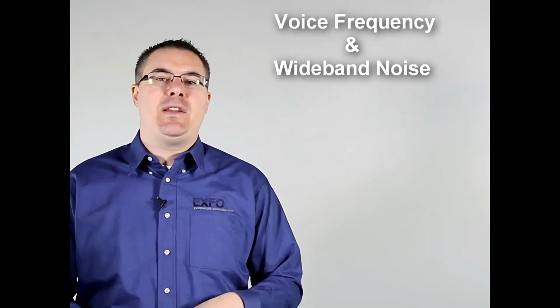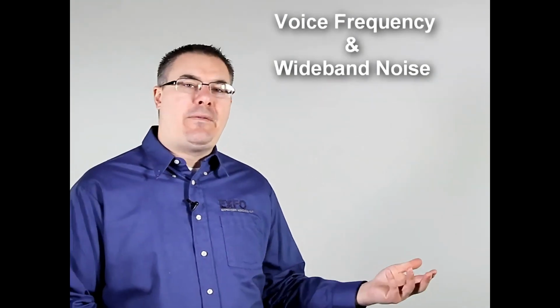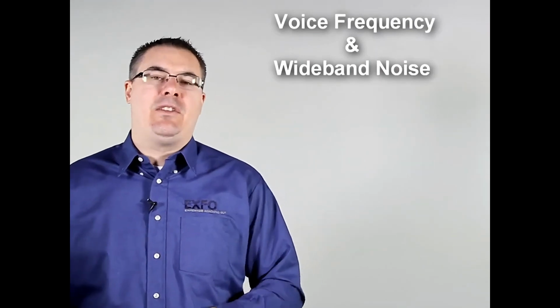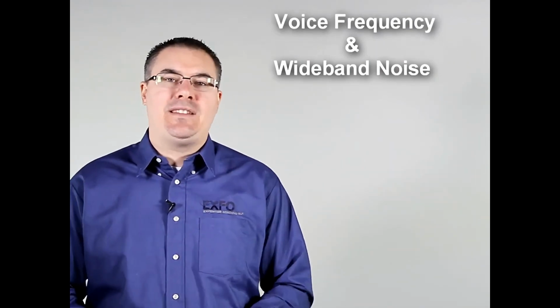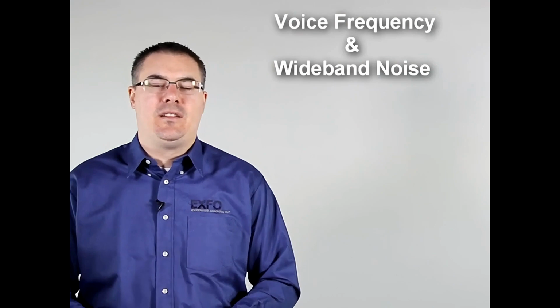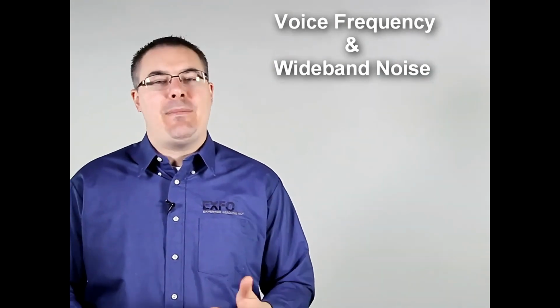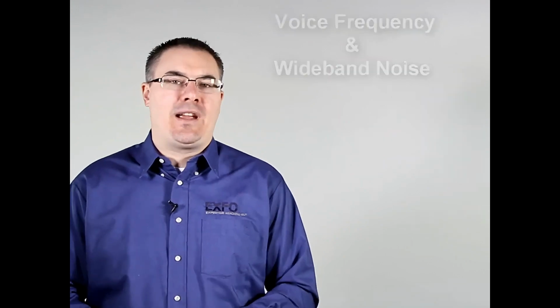Today we'll be discussing the different types of noise, so VF, voice frequency, WB, wideband, and their respective PSD, power spectral density, and impulse noise tests. We'll be discussing what they are, the difference between them, how to measure them, and how to use results to recognize disturbers using EXFO's MaxTester product line. First, we'll begin with VF noise.